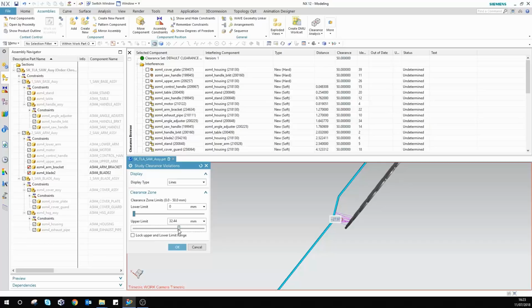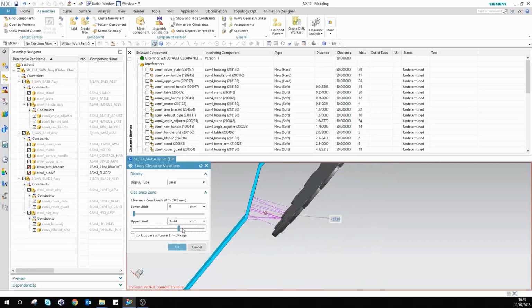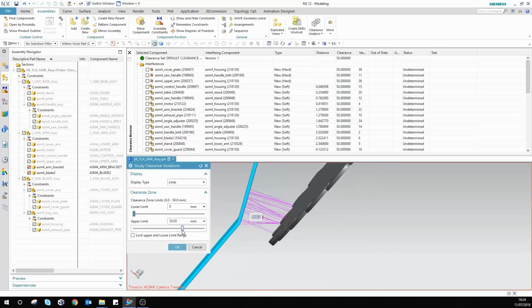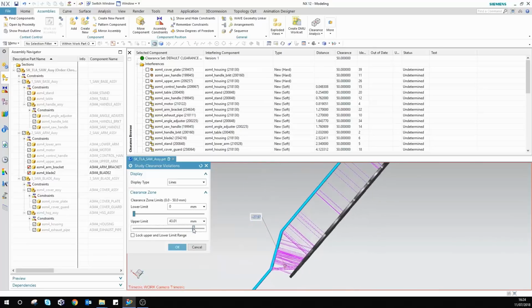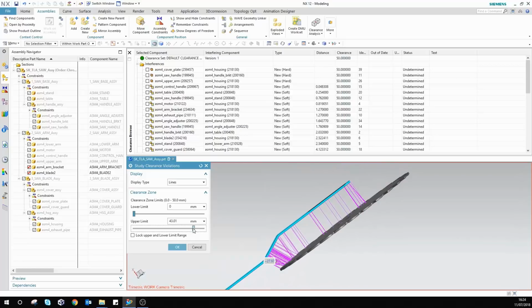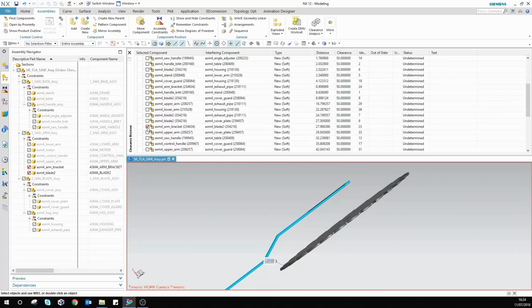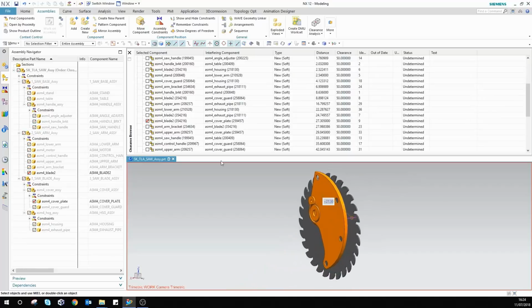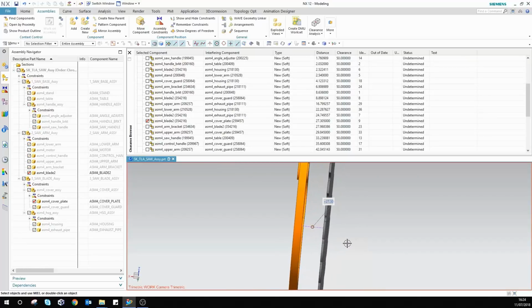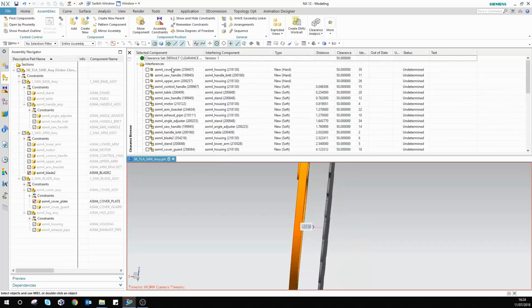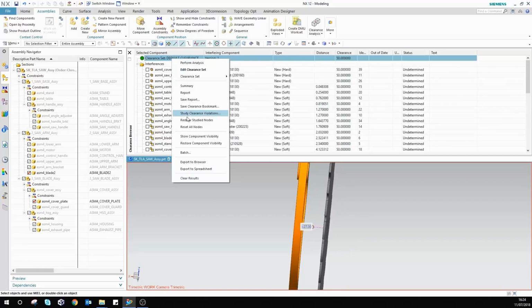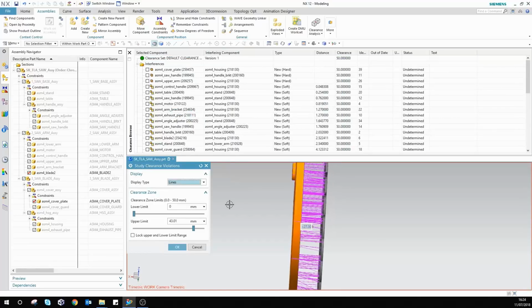If we start to get a little bit further past here, so we're up at about 32 millimeters here, you'll start to see the extent and the range of where these are going to come through. So you can use these study violations on these ones as well, and they will be available for all the different bits you pick up in here. Again, this one's about 27.5 millimeters. Just coming back to the top, study these clearance violations. Bring these in. Again, changing this slider will show you the distances between the two.